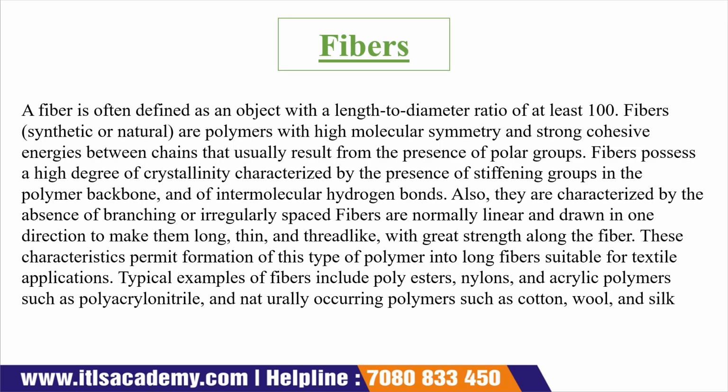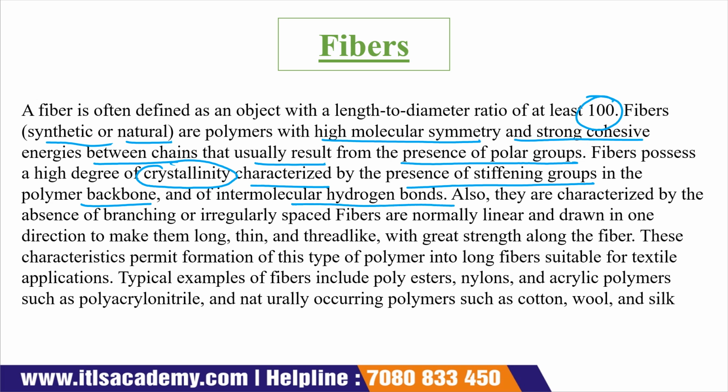Now the next is fibers. Fibers are typically defined as objects with a length to diameter ratio of at least 100. Fibers are either synthetic or natural. They are polymers with high molecular symmetry and strong cohesive energies between the chains that usually result from the presence of polar groups. These fibers also have a high degree of crystallinity, characterized by the presence of stiffening groups in the polymer backbone and intermolecular hydrogen bonds.